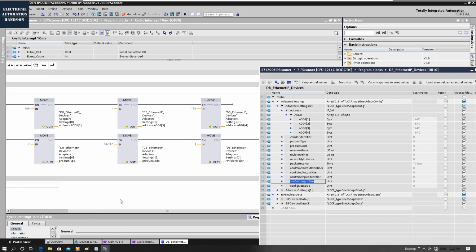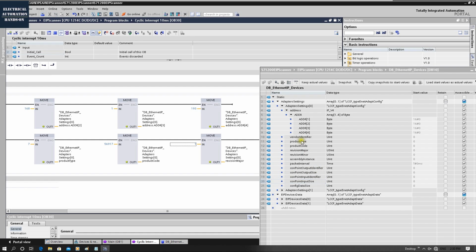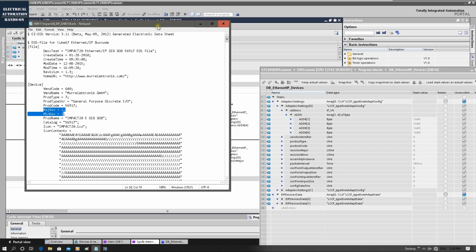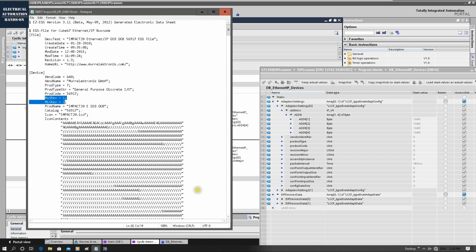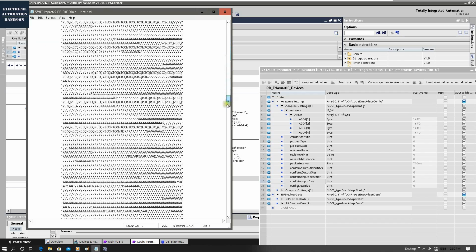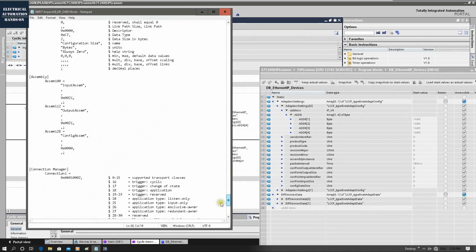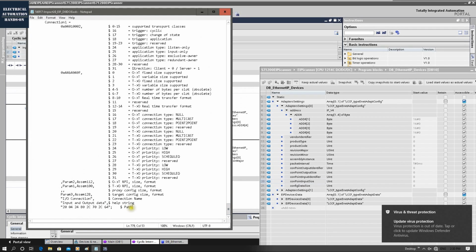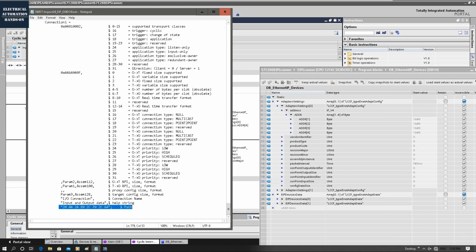If you have some background knowledge from Allen Bradley Studio 5000, you can recall when you set up some devices, especially a device that doesn't have the EDS file, you probably need to set the input, output, and config assembly ID. Here, I highly recommend you go back to the manual, which explains those parameters in great detail, such as how to translate the assembly input, output, and configuration numbers using the data at the very bottom line. And personally, I would recommend we go to the web page of this Ethernet IP device, where we can see the assembly number and input output values directly.